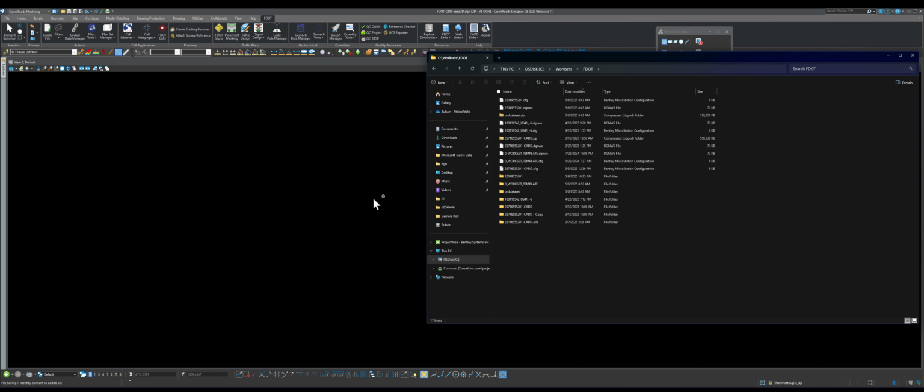In that video, I explained exactly what to do: how to mimic that, make up an empty template folder, and then bring the DGN, NWS, CFG files from ProjectWise here, and then bring your file from ProjectWise here locally, and then use the tool, get your numbering, get your stuff, and then select the file and bring it back to ProjectWise.